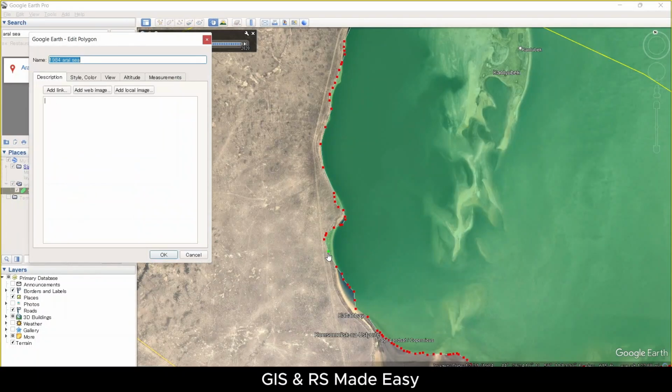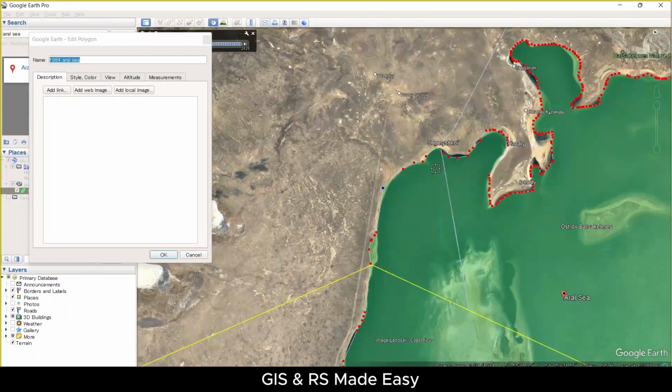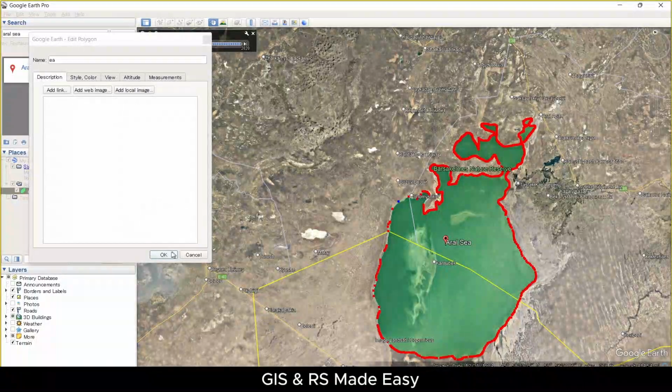Now select the vertex where we need to make the fix, and you can also select and repeatedly delete some points so that it will be okay. We can also delete some points here, and when you are done, you can make some points by clicking on the line and dragging to make it correct. When you are done editing, you can press OK.